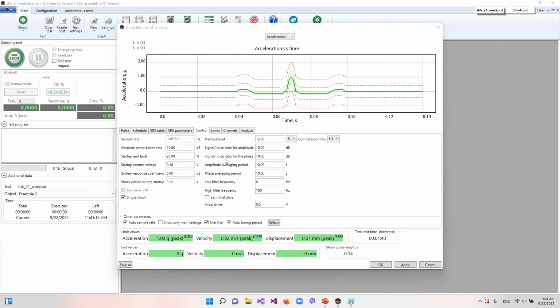And there's also a question here connected. What is the best location to mount control accelerometer? Personally, I recommend to place it in the center of the shaker's table. For example, our shaker, which we regularly use, has a hole for the stud in the center of the shaker's table, and in that case, you'll get the correct data. So the best location is on the shaker table, right?